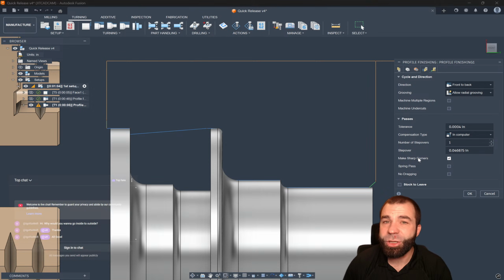Now, things have changed a little bit going from roughing to finishing, because you're going to notice, although we can do multiple step overs, we can't necessarily define other things. We cannot change and define things like being able to do our max optimal loads, our roughing cycles, chip breaking, as you're seeing. But because this is a finish pass, we now have the ability to go in and do some things like turn on cutter comp so that you can adjust it at the controller.